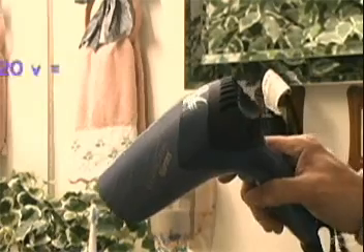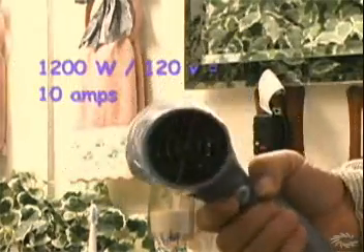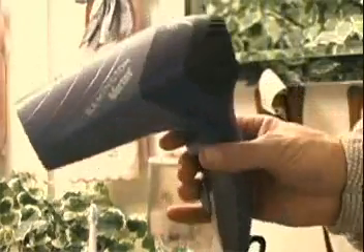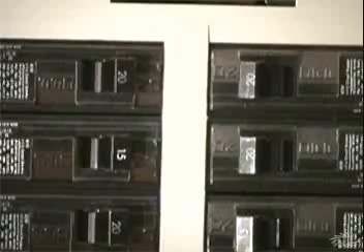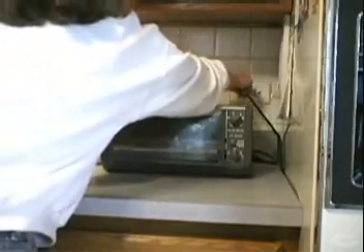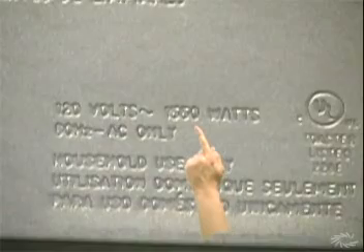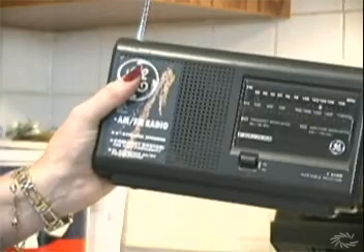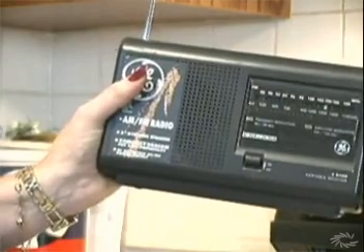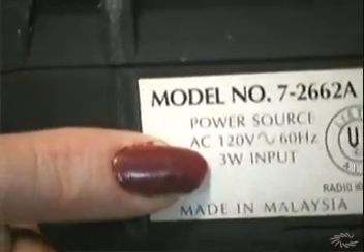However, the hairdryer rated at 1200 watts will have an amperage of 10 amps. That means in a 20-amp circuit, we can't have other devices that use a lot of amps plugged in and turned on at the same time as we use the hairdryer. Otherwise, the circuit breaker may trip. You can find the wattage of most electrical devices on a special identification plate found on the back, side, or bottom of the appliance. Let's look at a few common appliances and compare their wattage. Remember, the higher the wattage, the greater the amperage. Things with higher amperage shouldn't be plugged in at the same time.